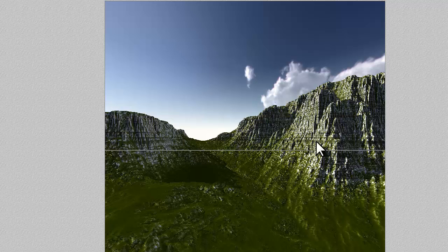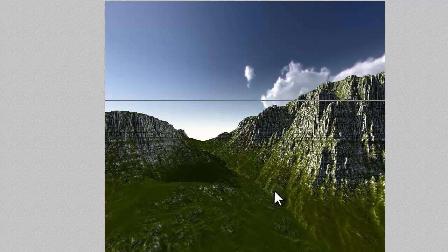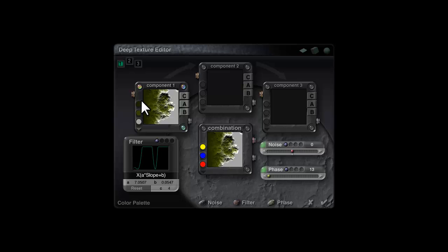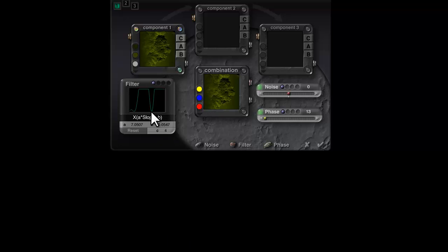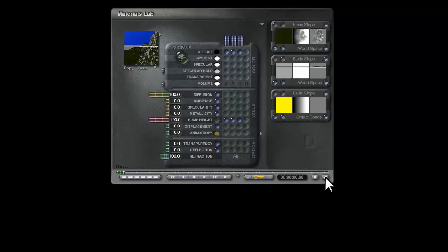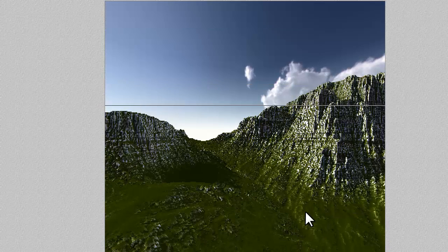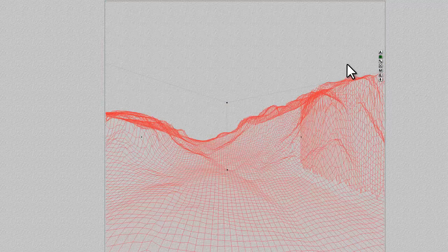And you can see now that the curvature filter's exposing these rocks on the outside and creating channels in the middle there, and the slope filter's putting this ground texture in. Now, I said we can incorporate curvature filtering and colouring at the same time. So if we switch from linear interpolative to curvature, we can have the slope filter and the curvature filter active at the same time. Though things start to get a bit complicated then, and you can see I've applied this, but it's not really that clear which colour is being put where.